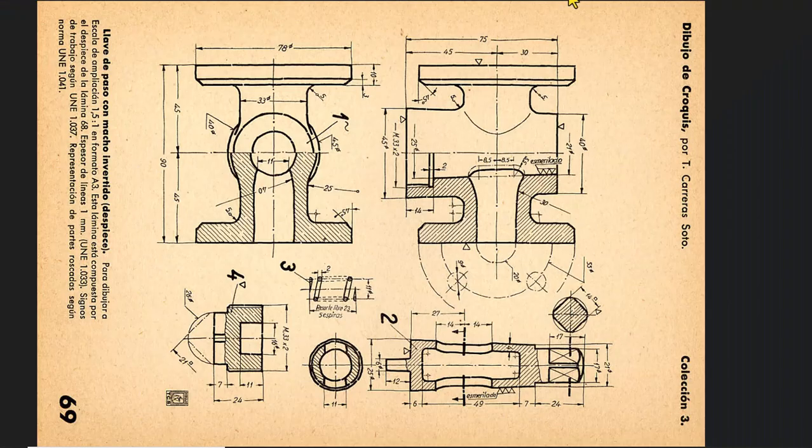Now we want to create this internal volume, which has a thread to the left, a cut, and a sloped or conical internal volume. We don't draw now dimensions for the thread because we create this contour and we'll apply hole to create the thread.